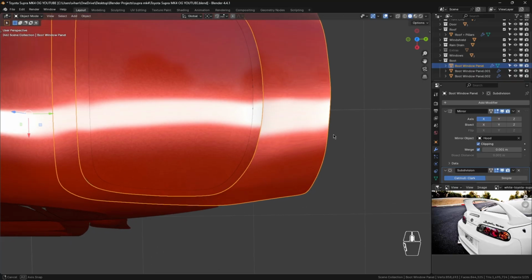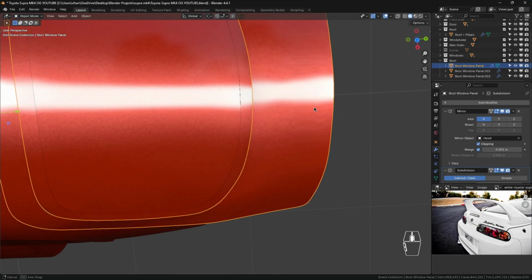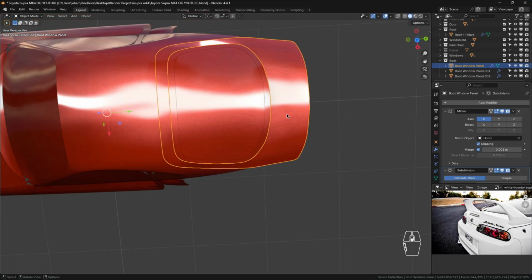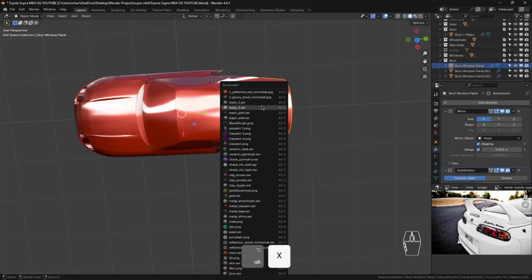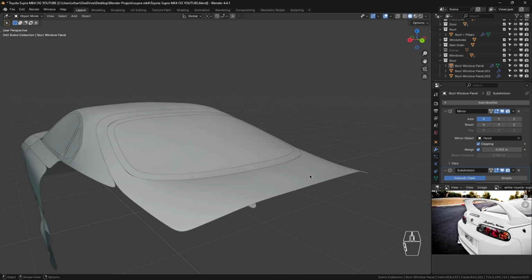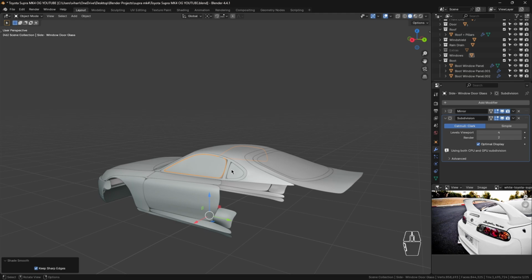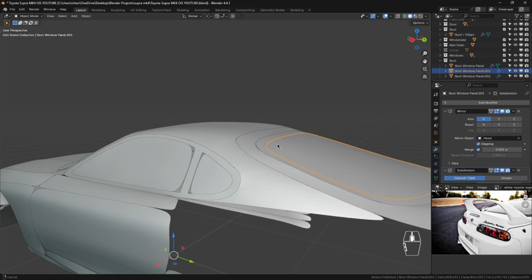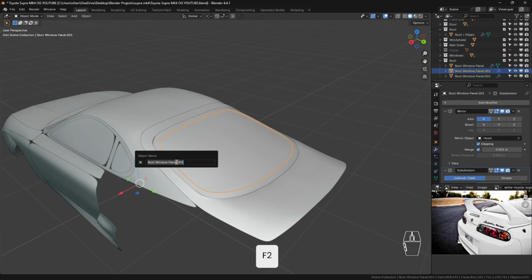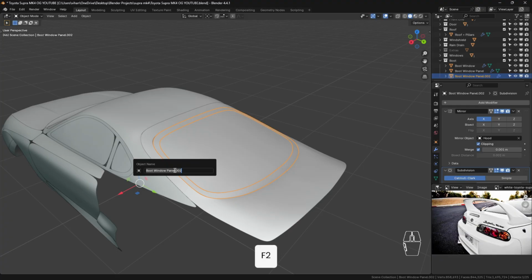Select the red ball matte cap and just make sure that this entire line of reflection is going continuous right here. Right? You see the continuous line? That is what we're aiming for. And you can just switch back to your basic. Right? There we go. That is our boot window. We've finished up with all of these. We've done those. Don't forget to rename these. F2, just boot window, and just rename this to boot window adhesive. The black part, black ADH.